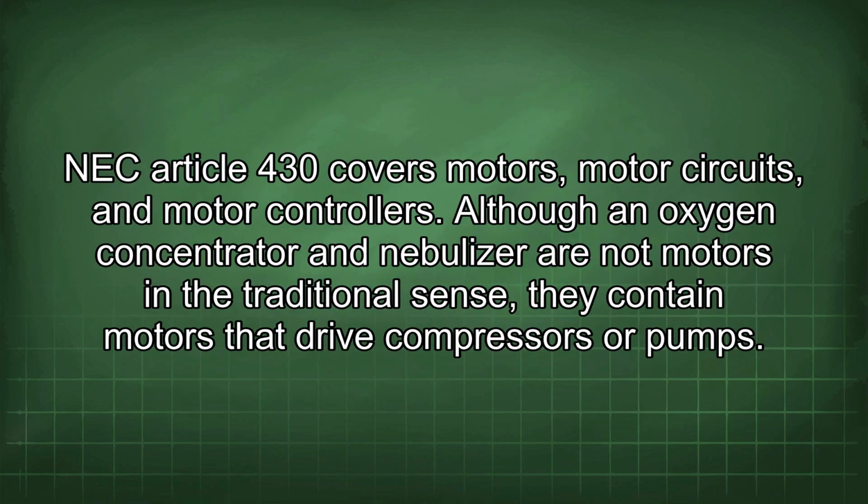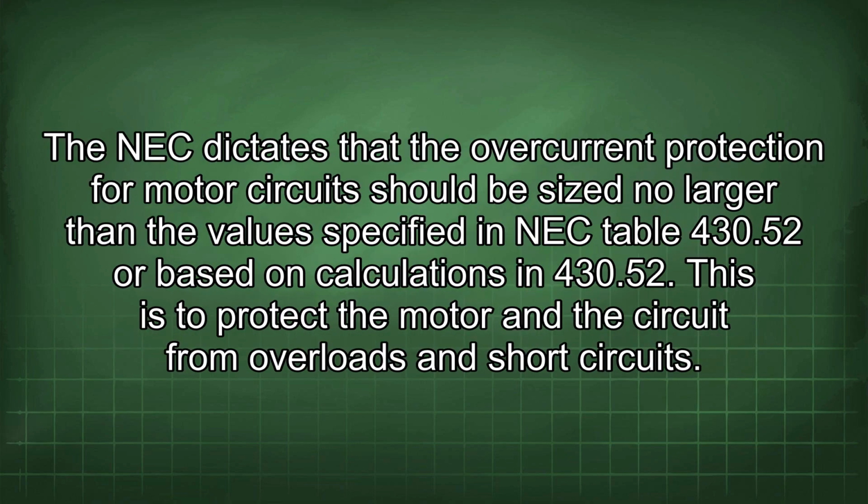NEC Article 430 covers motors, motor circuits, and motor controllers. Although an oxygen concentrator and nebulizer are not motors in the traditional sense, they contain motors that drive compressors or pumps. The NEC dictates that the overcurrent protection for a motor circuit should be sized no larger than the values specified in NEC Table 430.52 or based on calculations in 430.52. This is to protect the motor and the circuit from overloads and short circuits.